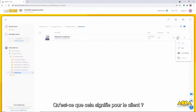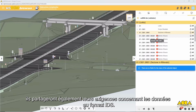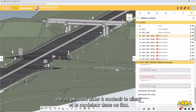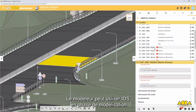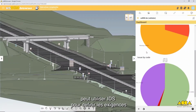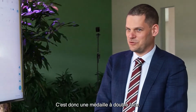What this means for the client is that now, every time they require an IFC model, they also share their data requirements in the IDS format. Tools that make use of this standard are very important, as they can help both the client and the modeler in their flow. The modeler can use the IDS in the modeling phase and be sure that the model will contain the required information. The client, on the other hand, can use the very same IDS for defining requirements and checking of the model, all in an automatic way. So it's a two-sided medal.